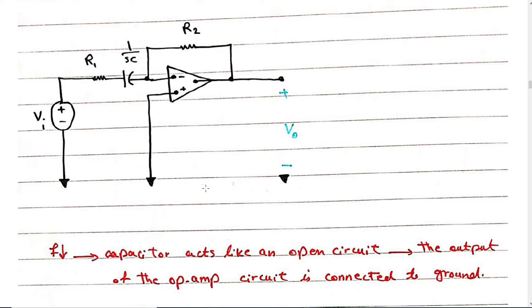Justin? So it would be a high pass because when the frequency is really high, the capacitor would act like a wire and just let the current pass through. Whereas when it's really low, that becomes an open circuit and doesn't let anything through. Okay, you said at high frequencies, the capacitor acts like a wire.